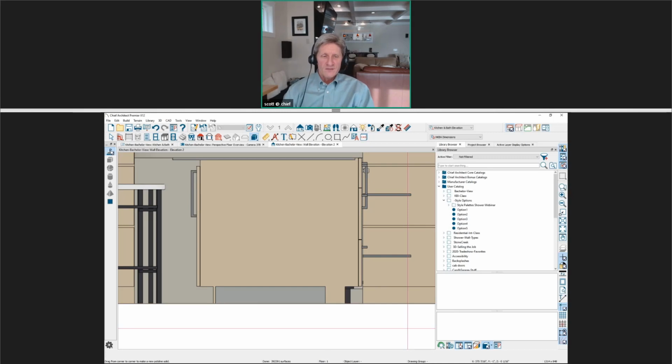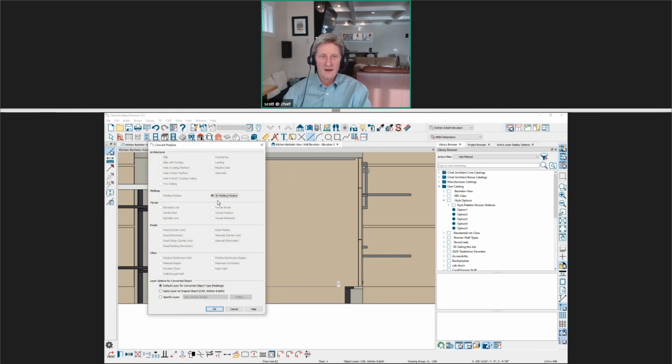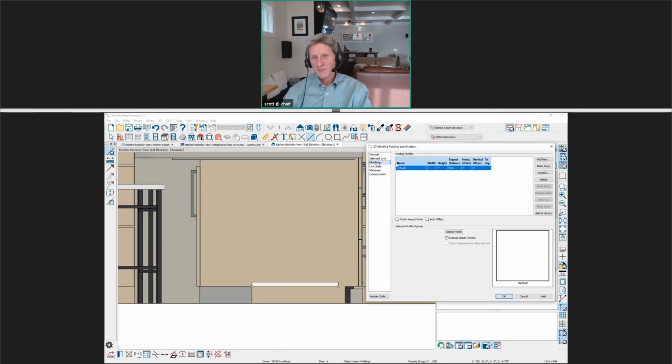And this would just assume that I'm not using a profile on it. And there it is. If you do want a profile on it, then you can. Let's just do it both ways. So we'll slide this over. You can use the molding polyline. I'm going to use the line tool and we'll just pick up the line and then I'm going to convert that line. Then I can put any sort of profile I want on it. So I've got this line drawn. I'm going to come into the lower edit menu down in my toolbar, convert that into a molding polyline. And then at that point, you can assign the molding profile that you want to it.